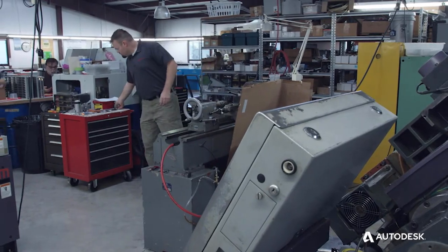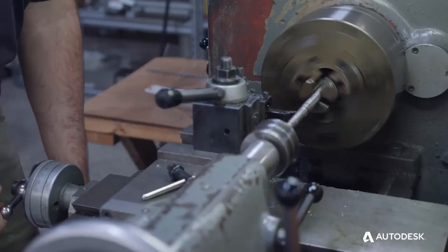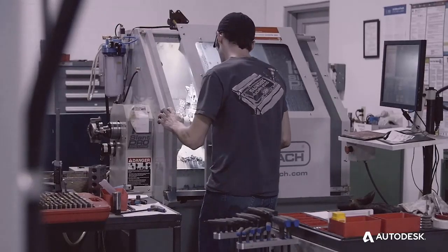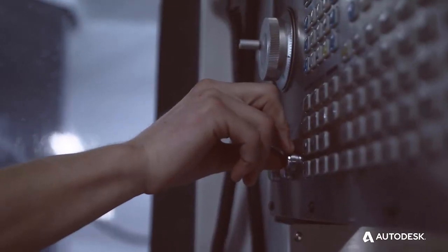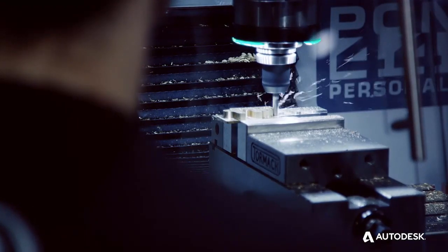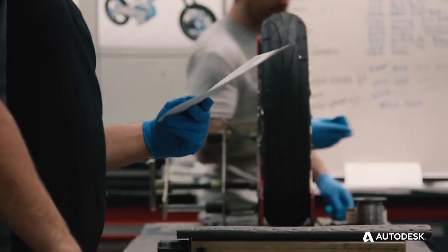The basic parameters used when determining the path the tool will take are step over and step down. The step over is the lateral or radial amount of material the tool is removing. Step down is the vertical or axial amount of material the tool is removing. Manual mills and lathes, where the cut is controlled by hand, were once common, but are becoming harder to find as time goes on. Now subtractive manufacturing is often achieved using a CNC machine, where the cut is executed by a small computer called a controller. This is where CAM software enters the picture, as the code the controller executes is generated using the CAM software.